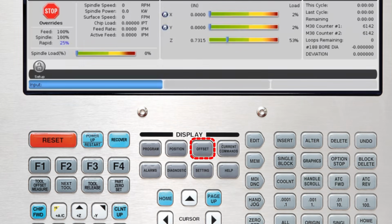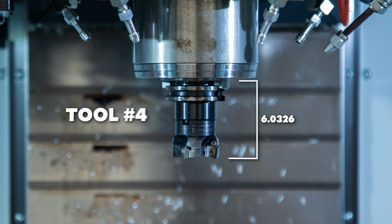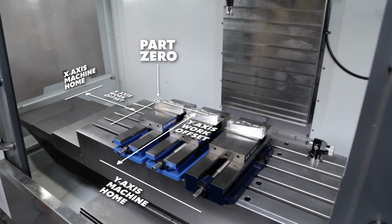Offsets opens up the menu system containing your work and tool offset numbers. The tool offsets are the number values that tell the machine exactly how far each tool sticks out from the end of the spindle. And the work offset is the number value that tells the machine where the workpiece is in relation to the machine's home position.